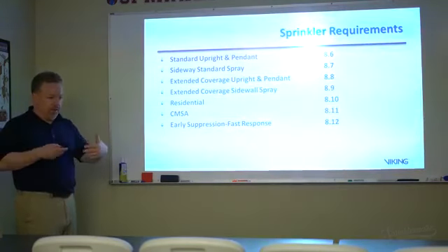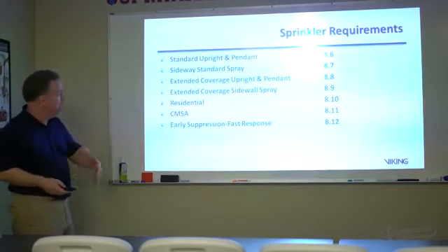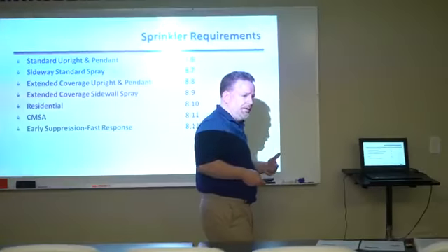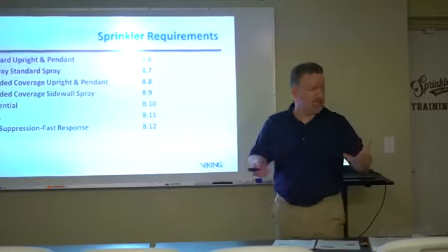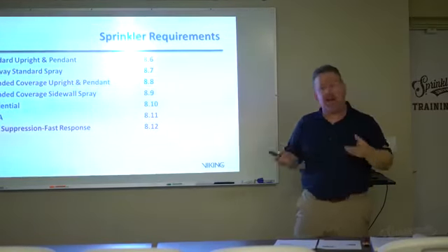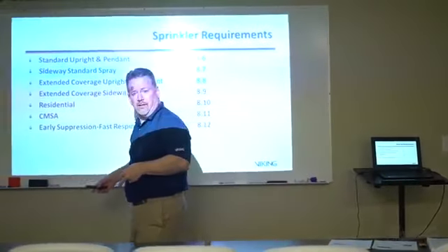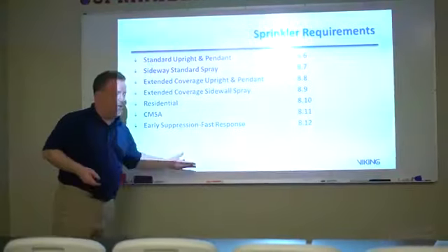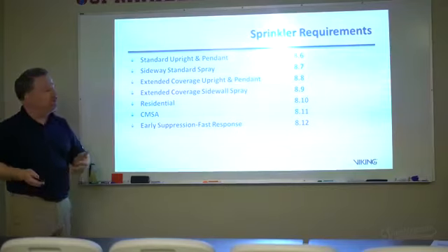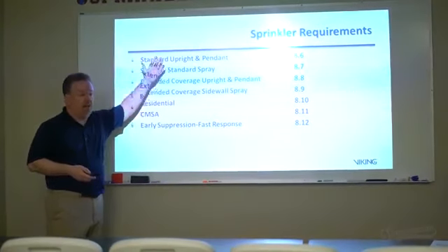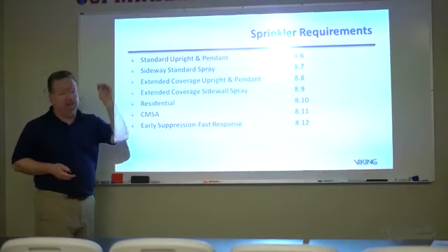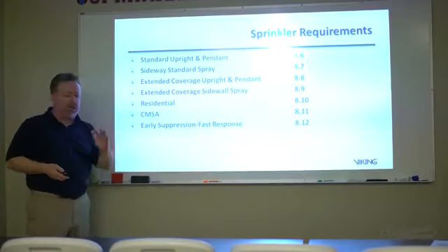I will tell you that there are certain types of sprinklers out right now that aren't covered in here. One of them that we're going to talk about on Thursday deals with the protection of interstitial spaces, and the challenges that come along with that, and attic sprinklers. They're not in this list anywhere. They have special installation rules that come along with their listing, with the way they were tested. So when you're protecting an attic, you're not going to NFPA 13 per se. You're using 13 as the base rules, but then you're following the specific listing rules for those sprinklers in those areas.